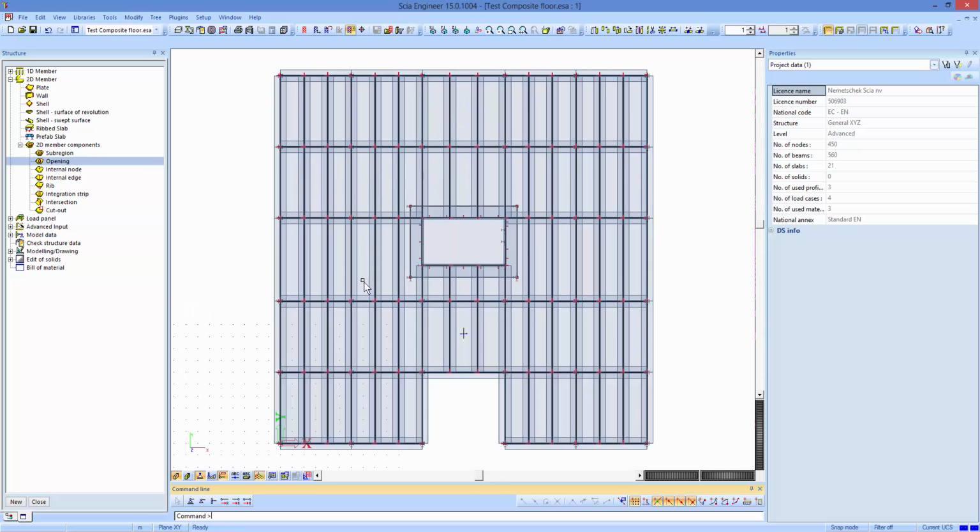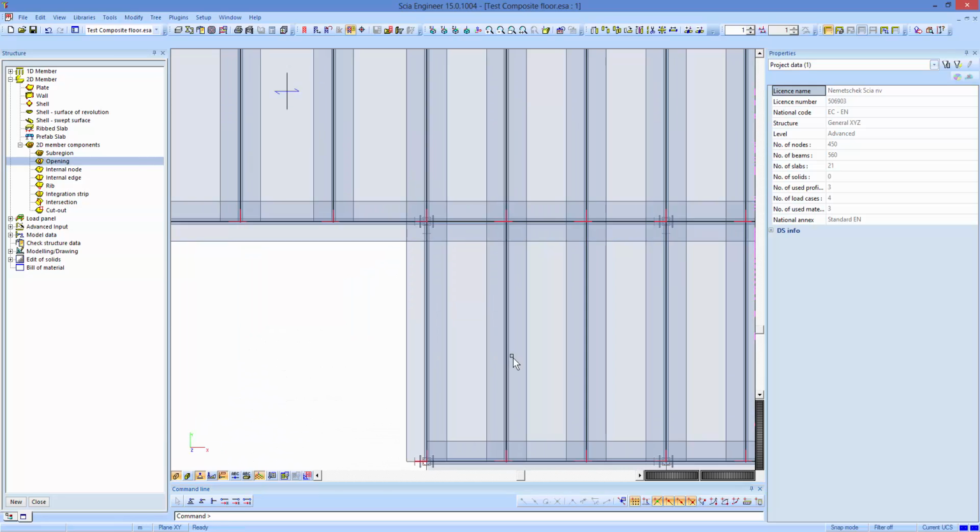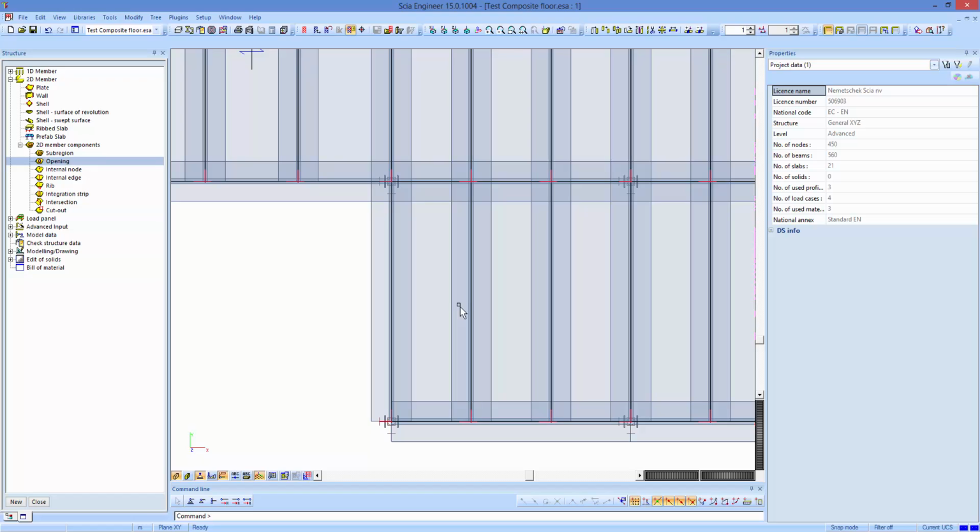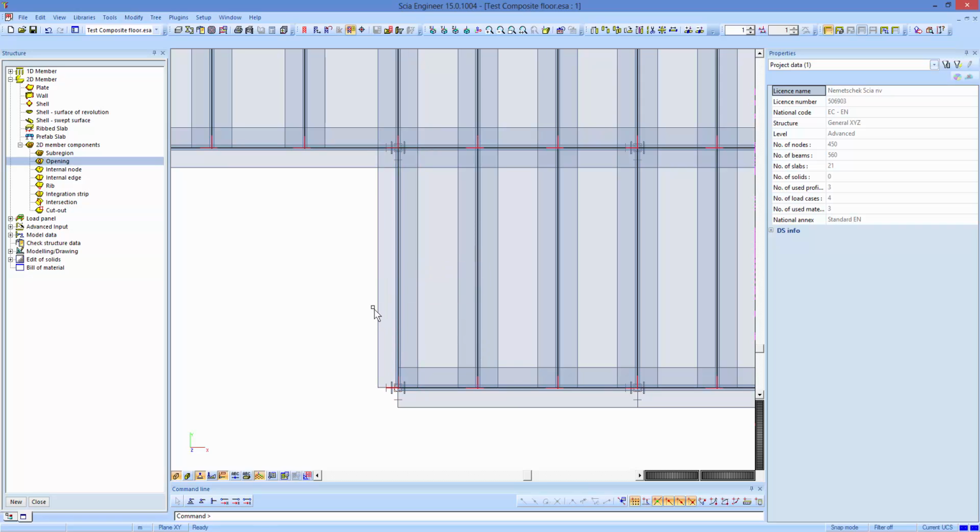And I will quickly use this view. You see in here, this is the effective rib that he is going to use. This is not the one he's going to use eventually, because eventually he's going to do an automatic calculation of the correct effective rib. You also see that here, next to the plate, the effective width is shown.